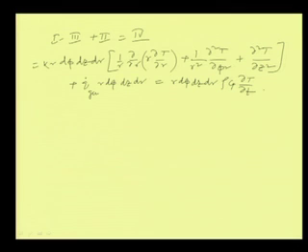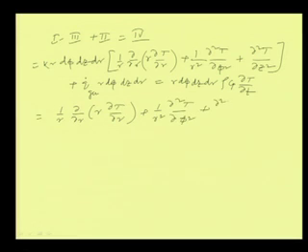Thus, if you divide by the volume element r dφ dz dr as we have done in the previous case, what you are going to get is 1 by r ∂/∂r of r ∂T/∂r plus 1 by r square ∂²T/∂φ² plus ∂²T/∂z², and that is equal to q dot generation by k plus 1 by alpha, sorry, this is plus, and this is equal to 1 by alpha ∂T/∂t.